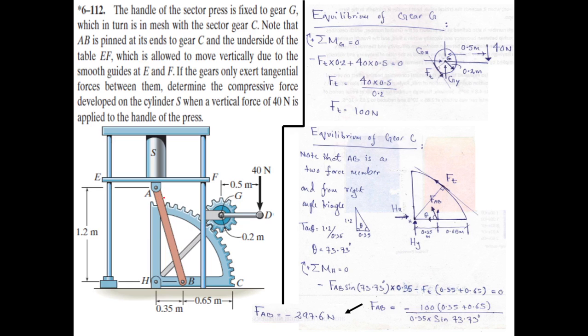So that is why, since the resultant forces at A and B are the same, I have shown the force in this member AB as a single resultant force FAB, right? And I have used a tensile direction, positive direction, acting away from point B. It is also arbitrary, so if you want to assume a compressive direction, then you have to use compressive like this, towards point B. So compressive is towards point B, tensile is away from B.